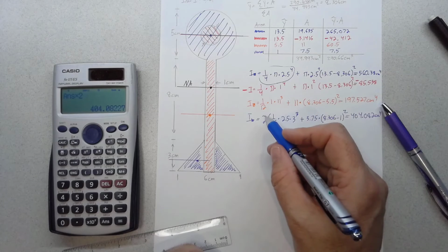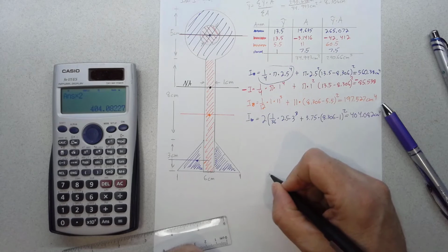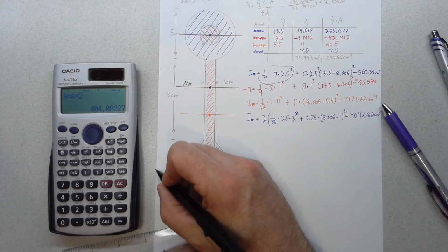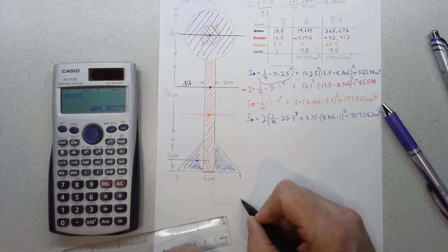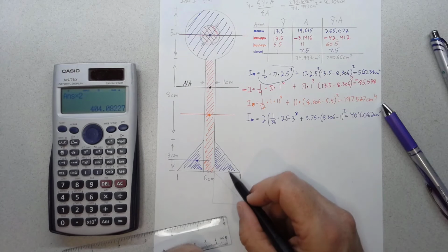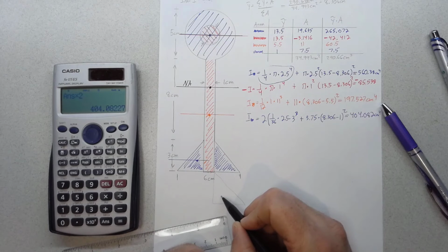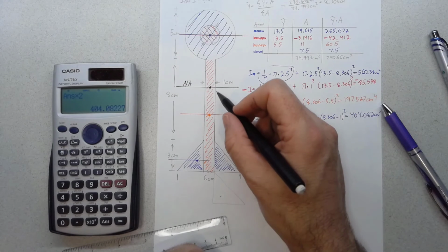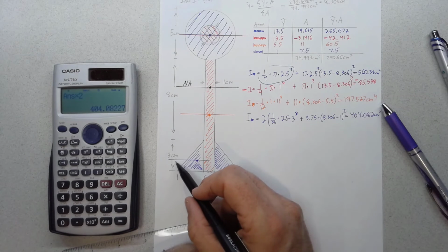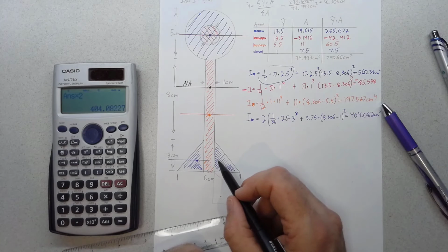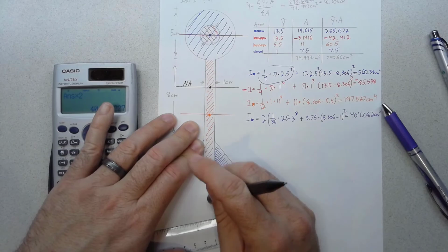I could multiply it times 3 if I had some weird shape that had another triangle right out here, or times 4 if I had another triangle over here. The key idea is, let's say I had another triangle right here, even though the area of the triangle is the same, I can't just add that on as a 3 here because its centroid is a different distance away from the neutral axis than this one is. So when things share a centroidal axis, you can just multiply them together. You can't if they have a different distance from the neutral axis.